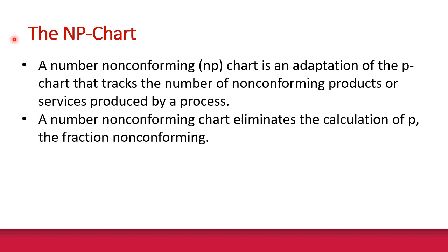Okay, so let's look at the NP chart. The NP chart is similar to the P chart, but it's an adaptation of the P chart that tracks just the number of non-conforming products. It eliminates the calculation of P, the fraction non-conforming.